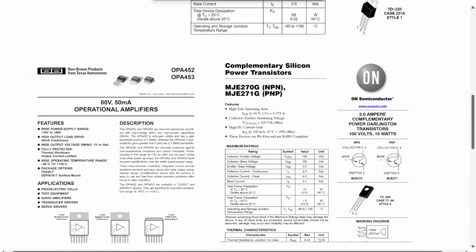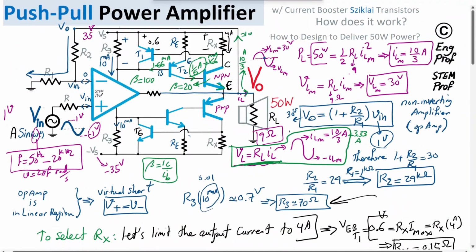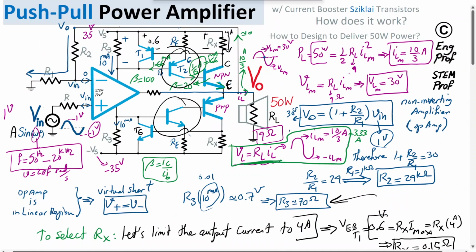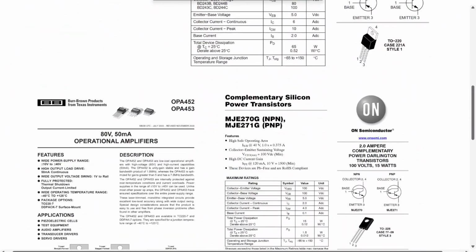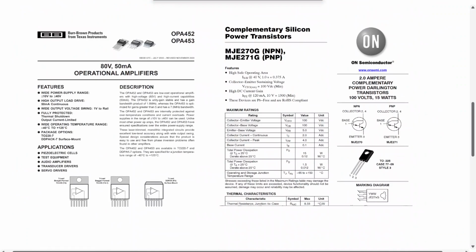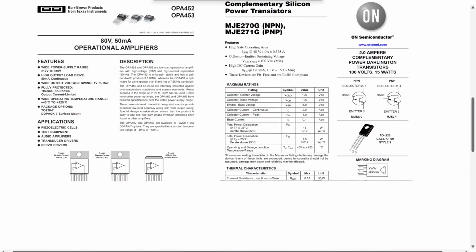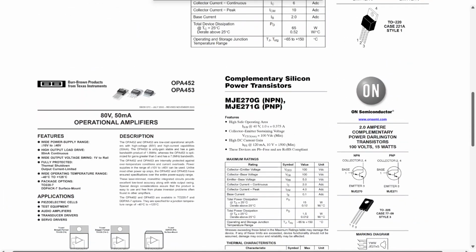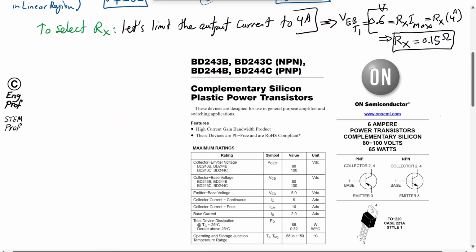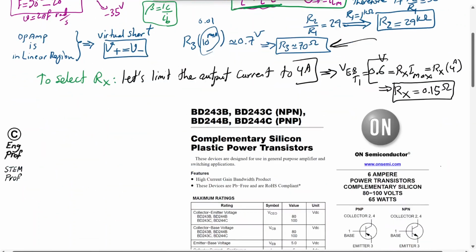Now for the smaller transistor, I mean the second transistor, the smaller one in the Sziklai pair, the PNP on top and the NPN here, since we just need 166 milliamp max collector current, there are many options we can possibly go with. I don't have an example on hand right now, but there are many options available to be purchased.